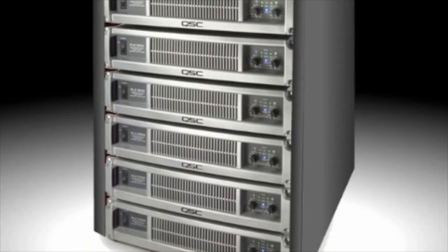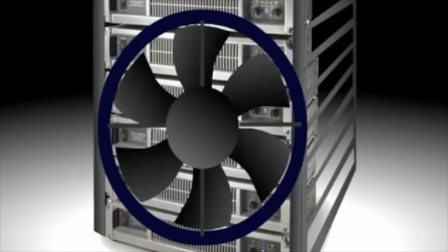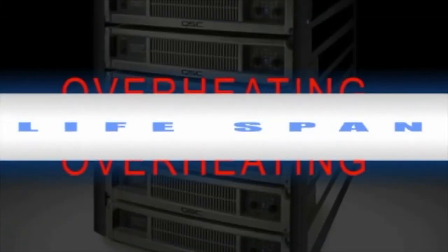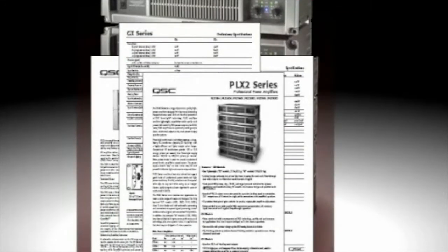The amount of heat generated by power amplifiers can be quite immense. Proper ventilation around the amplifier and conditioning of the room where the amplifiers are located is critical. Overheating greatly decreases the lifespan of the amplifier. Most manufacturers provide specifications and guidelines for proper heat dissipation.